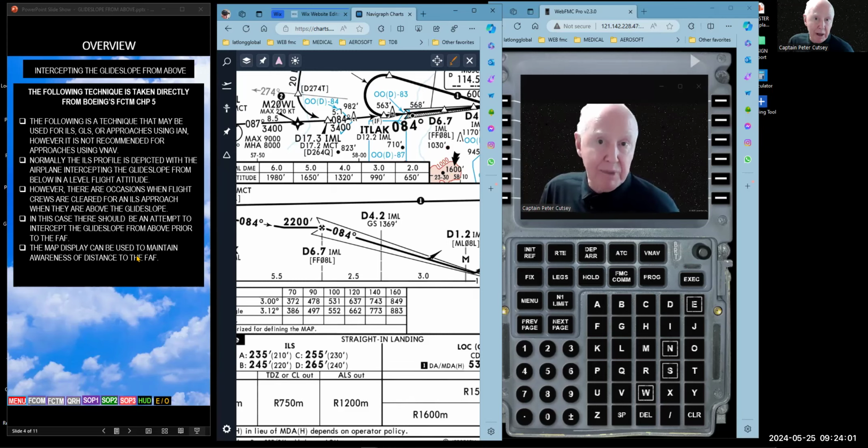Using the nav display will be a great advantage, especially in VS, to observe the arc with the vertical speed selected and at what position you will attain the altitude set in the MCP. That's what is meant by this paragraph. Use the autopilot.